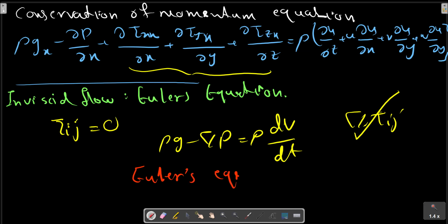Euler's equation for inviscid flow we showed in the previous section. Euler's equation can be integrated along a streamline to yield a frictionless Bernoulli equation. The complete analysis of the inviscid flow field using continuity and the Bernoulli relation will be described in the next chapters.